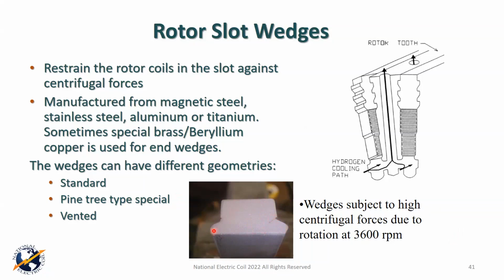And this is the dovetail fit. So all that weight is on this surface here, basically. This is just going in between the teeth here. But all that pressure put on it exhibited a crack, so obviously that had to be replaced.